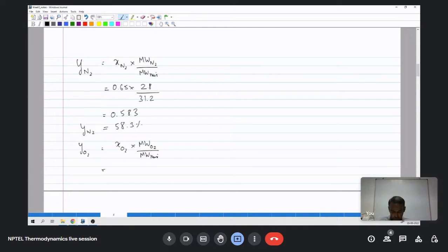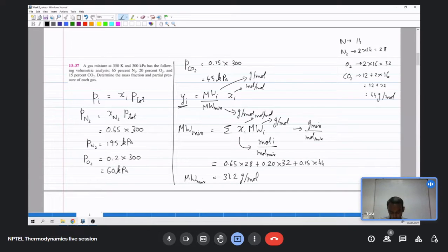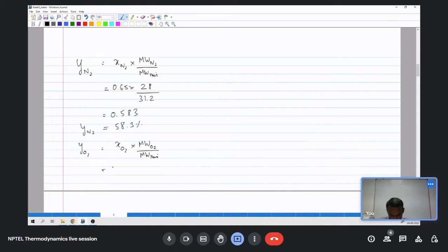No, sir. Okay. Now molar fraction of oxygen is 20%, so 0.2 into molecular weight of oxygen is 32 divided by 31.2. This is 0.205 or 20.5%.